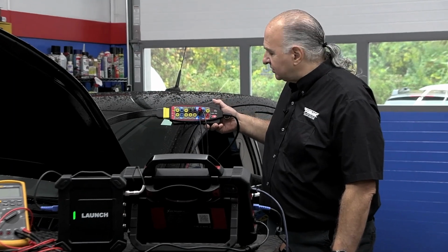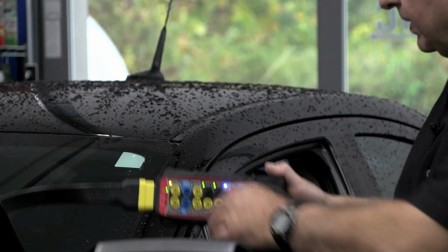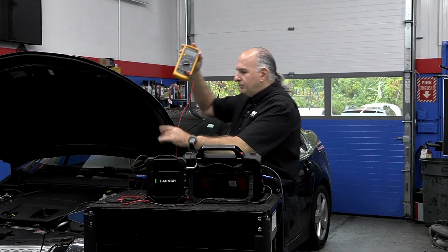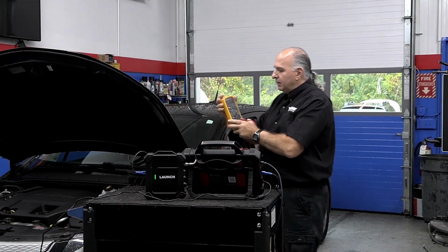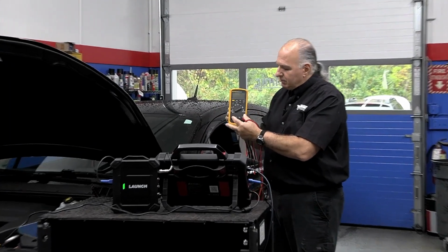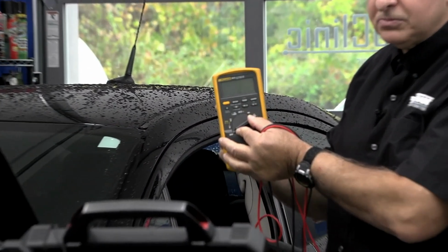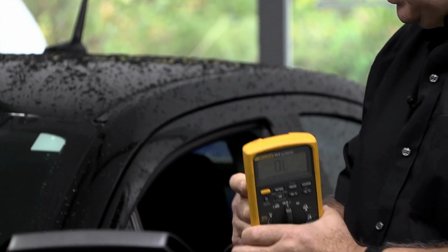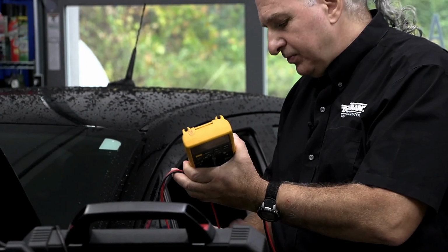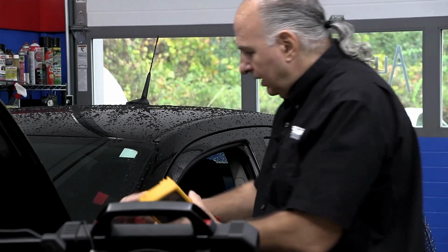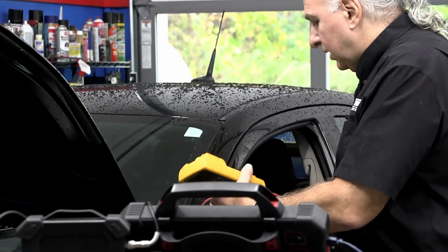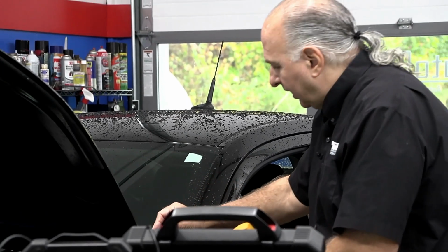Okay, so now you see how this is communicating? It's still beeping. It's not going to sleep yet. I'm going to unplug these leads. I'm going to take my meter leads, and I'm going to put my meter on ohms. I'm on the ohm scale. I am going to take the leads and put the red one in pin what? Pin 6, and the other one, the black lead, in pin 16.